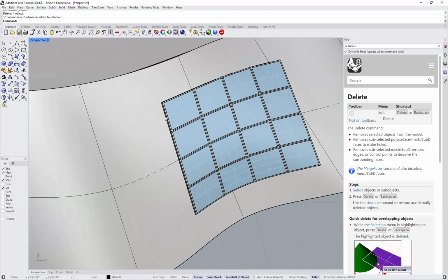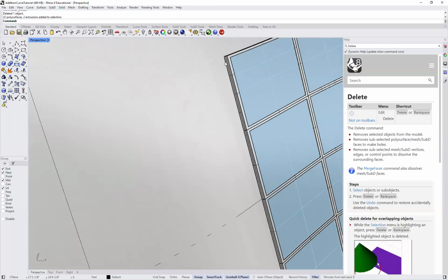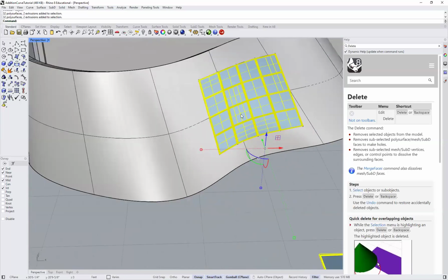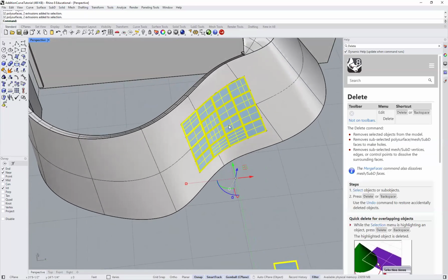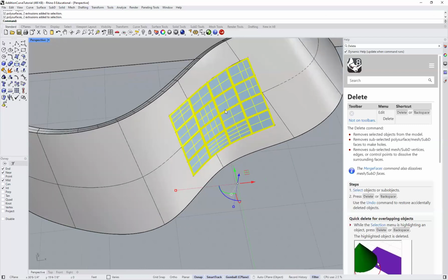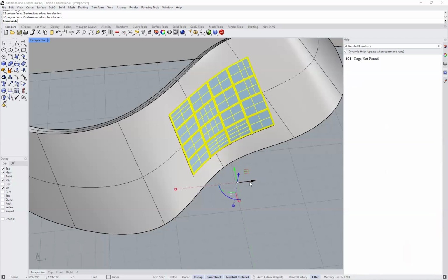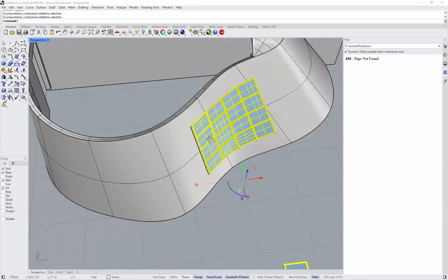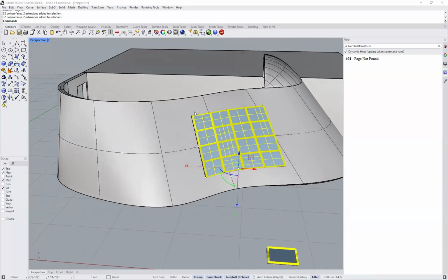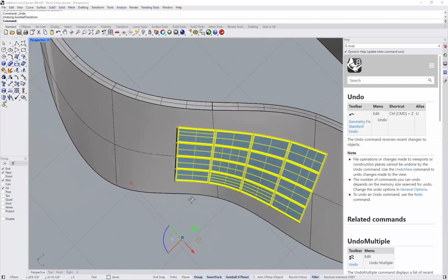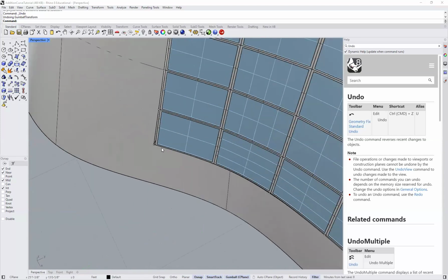The other thing, though, too, is that you might not want the frame to be sticking out because that does kind of look a bit odd. So what you can do with that is kind of wiggle it back. Remember, our wall is 6 inches, so we could kind of wiggle it back. So what I'll do is I'll move this up 1 inch, then I'll move it to the left another inch. What happened here? Let me undo that. That didn't seem right. So here we moved it.